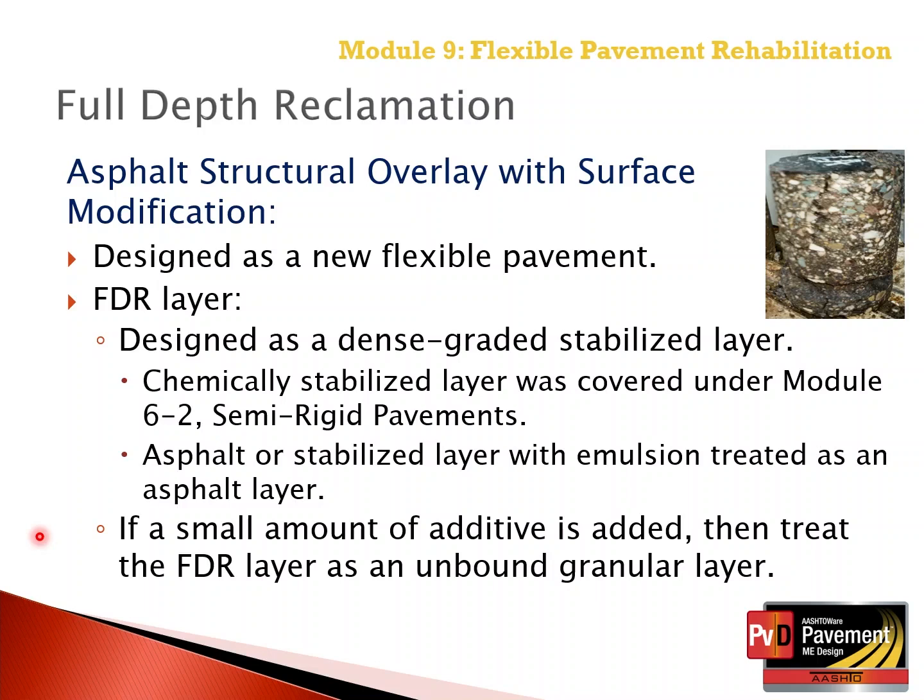And that treatment or simulation is explained on the next couple of slides. So in summary, as long as the full depth reclamation, as well as the cold in place recycled layer, is designed as a dense graded layer or bound dense graded layer, then that would be treated as a new semi-rigid pavement or new flexible pavement.